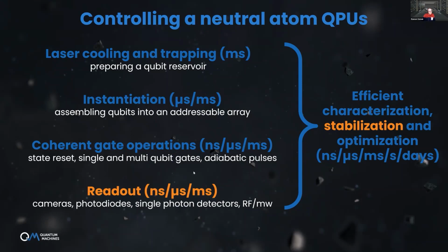Another feature I forgot to mention, maybe I should have shown this, is that the phase in the numerical oscillator used inside the pulse processor is per frequency. So if you play a certain pulse at a certain frequency, then you switch to a different frequency, and then you come back to the original frequency, you will come back to the original phase.